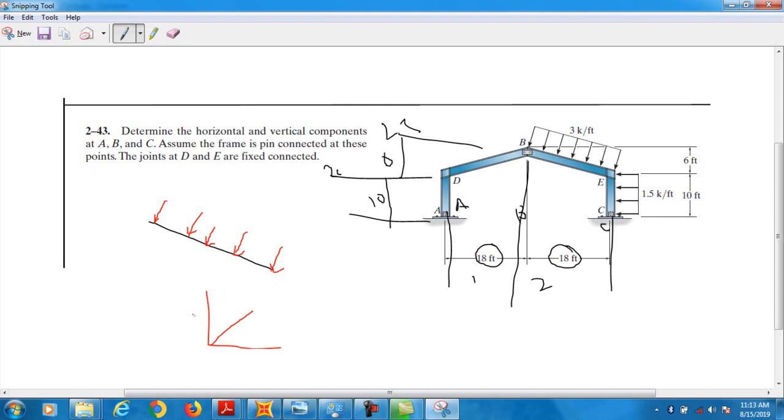If you select the gravity direction, the gravity direction will not be perpendicular to this element. There will be some load in this shape, which will be inclined to this member. So we need to apply this loading in this pattern, perpendicular to the line element.